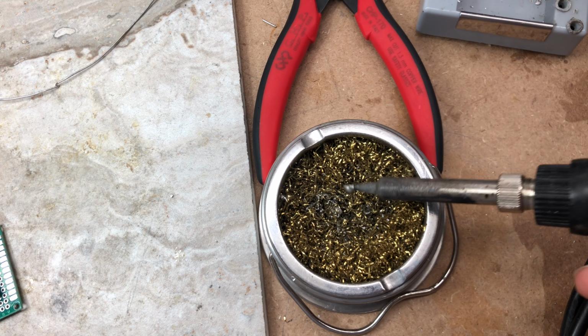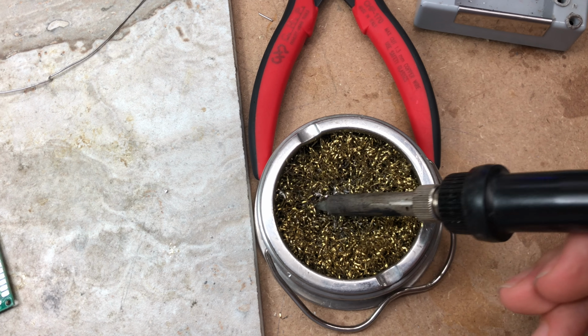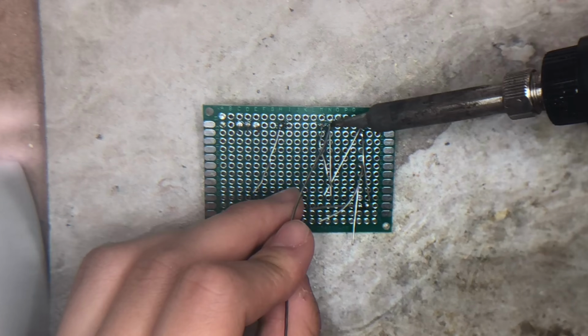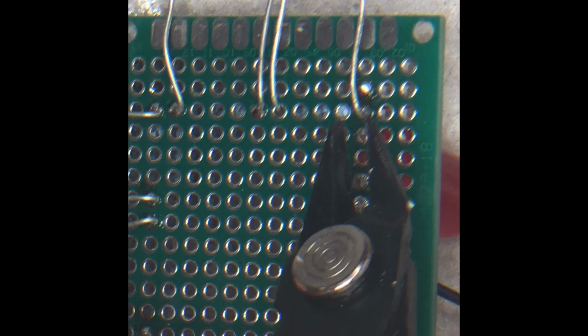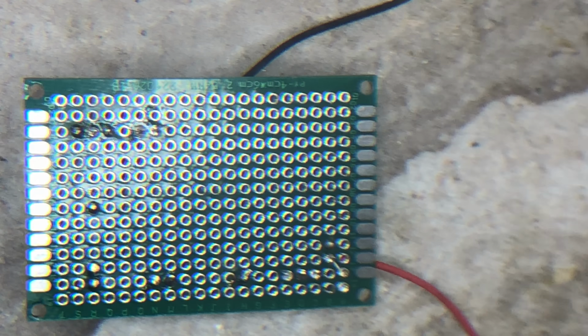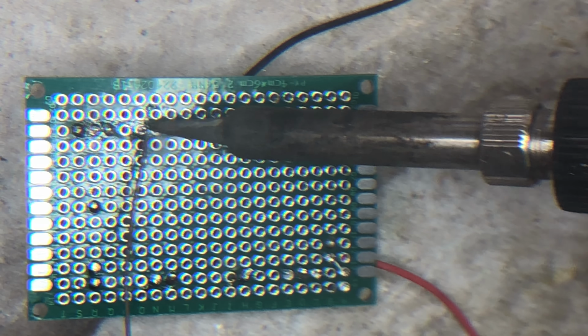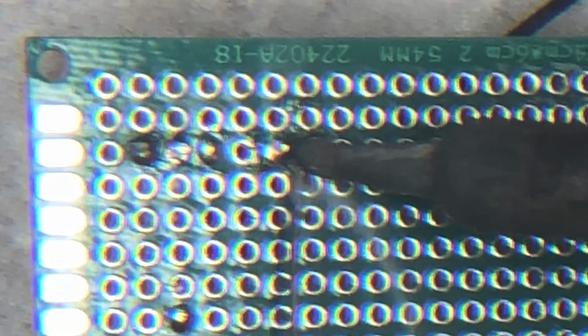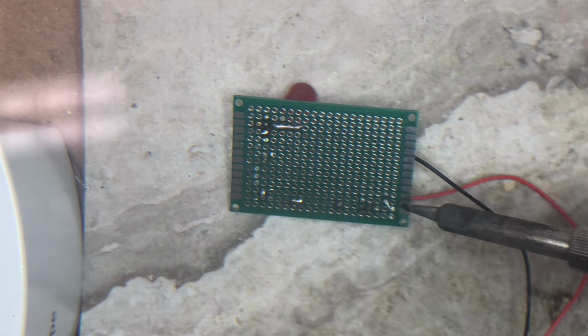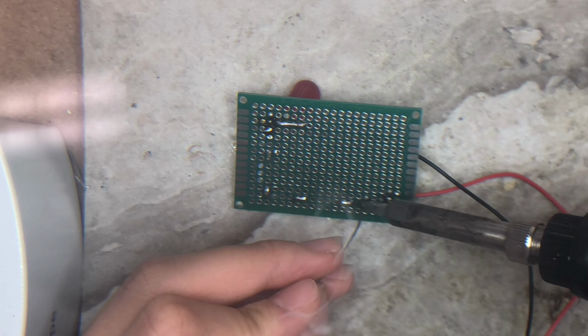When there's too much solder in your soldering iron, wipe it off in the steel wool. Initially, soldering will be time-consuming, but with practice you will improve. Use wire cutters to clip the components' legs. To connect components, you will need to make a solder bridge. A solder bridge is created when you apply excess solder between 2 previously soldered points.